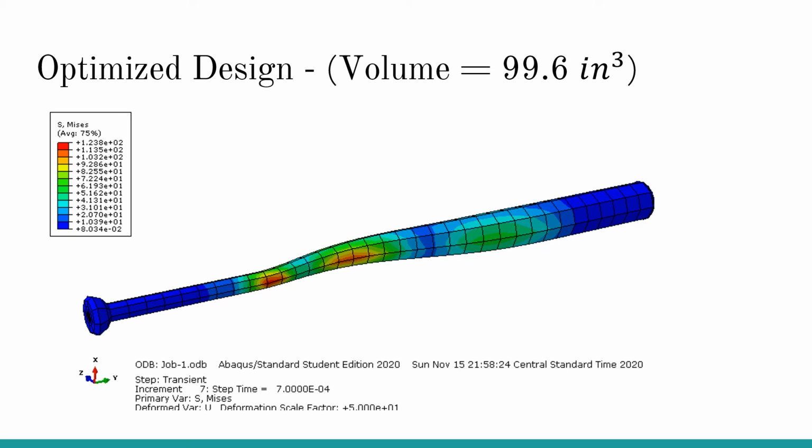43.9222. We expected the top to be maxed out just as it did because we realized when increasing the fillet at the top, that led to the most volume loss on the entire bat. And this led to, for the simulation itself, 123.8 psi as the max stress.